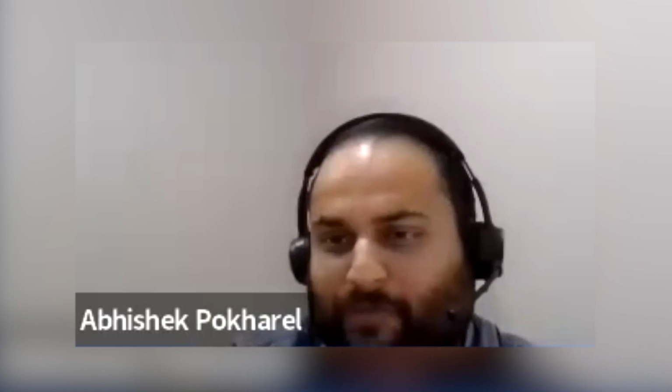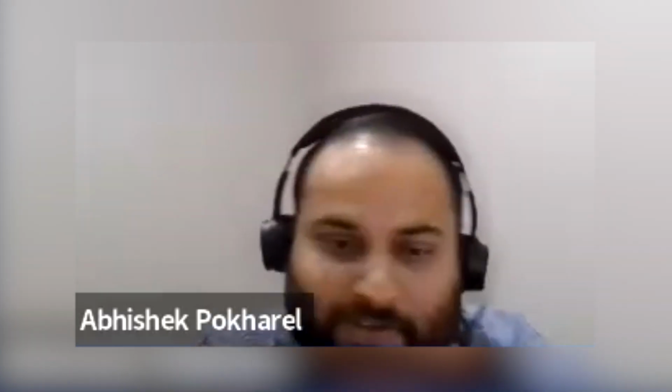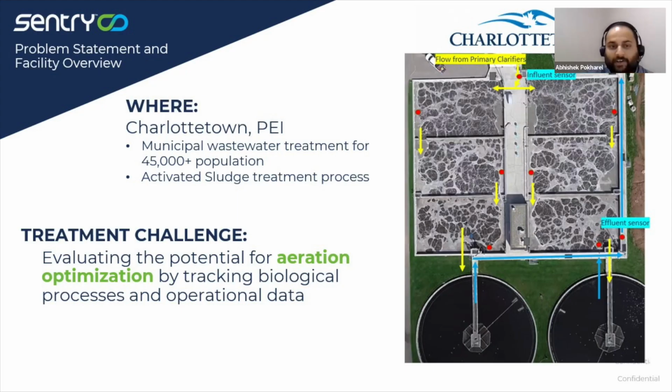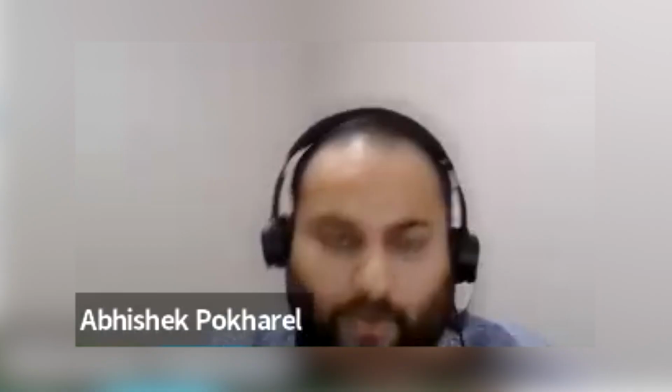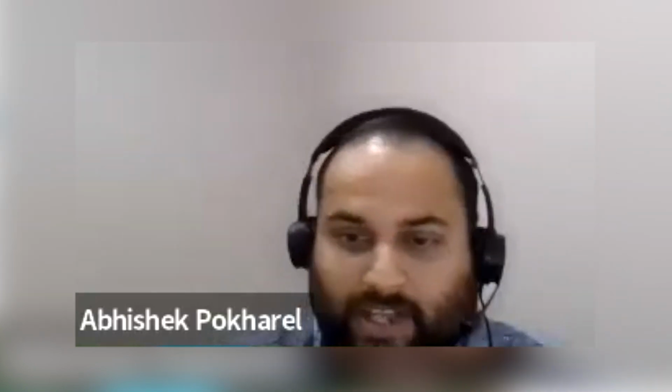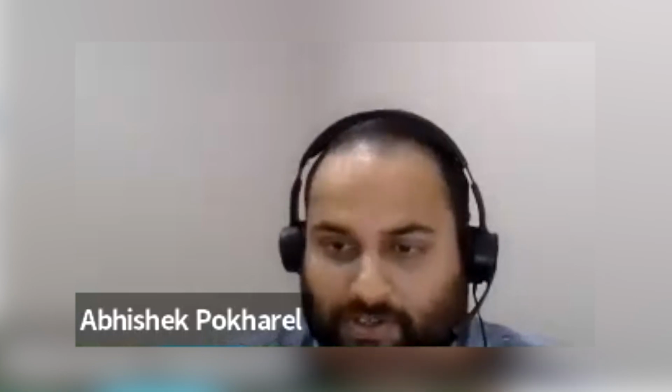Let's walk through the feed-forward aeration optimization using Sentry. This is the city of Charlottetown, our home base, my city, and we are at the treatment facility for the city. This treatment plant treats on average 45,000 population, but since it's a tourism city, the change in population is significant over the summers. With this, we have installed 8 sensors across the activated sludge treatment process of this treatment plant,